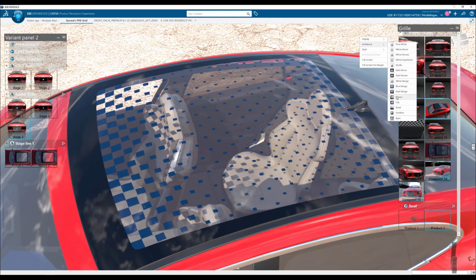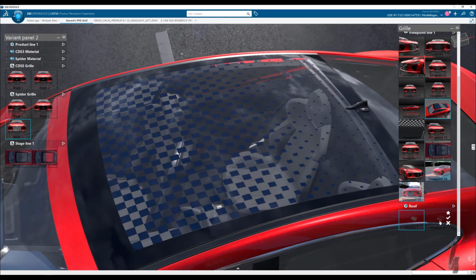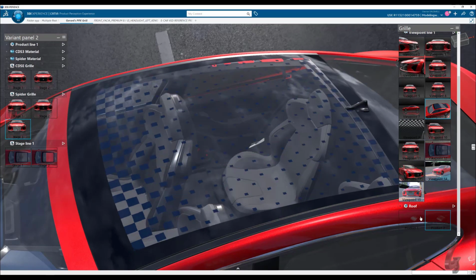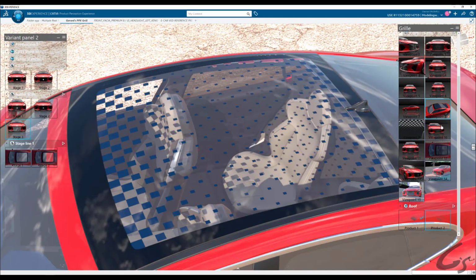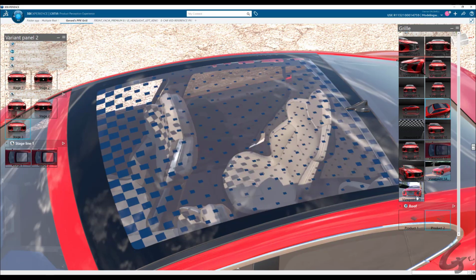So here you're able to review multiple variants, multiple different shapes or variants for a scene, multiple environments, color and trim options, different parts and configurations, specific views for reviews, and if desired, different part position variants, such as doors or hood opening and closings. And if you have access to kinematics, these can be implemented as well. And these behaviors can be set with triggers by mouse click, hotkey, or in VR by the selection from your wand.